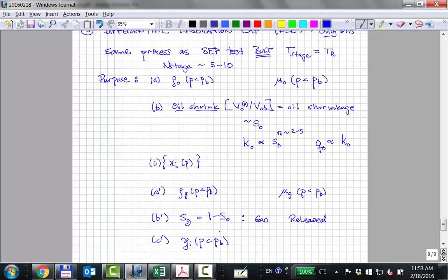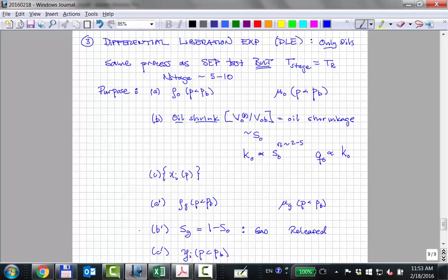Gas flowing is not as good as oil flowing, but you've got to take what you get. So you want to know how much propane, butane, and C6 plus heavy stuff is in the gas, because we'll extract that out as liquids at the surface. So you might be interested in the gas composition, and that's what this experiment, differential liberation, is trying to provide.